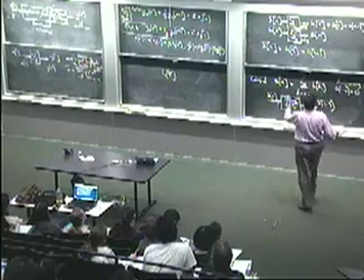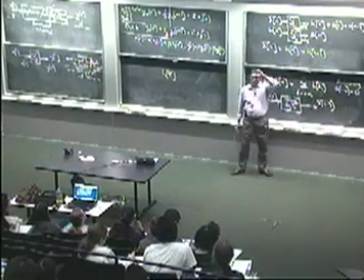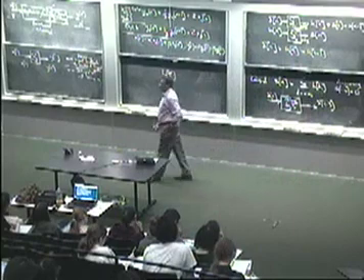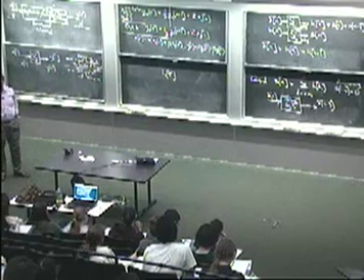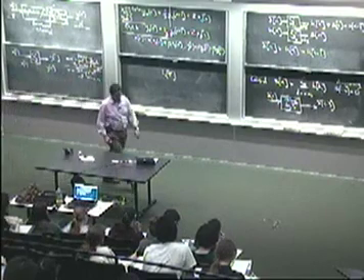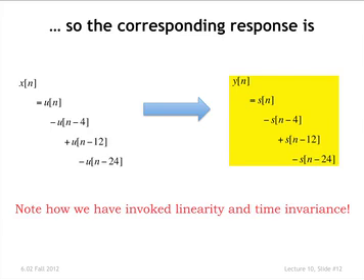So then it's back to this game again, right? If the input is a linear combination of unit steps, scaled and delayed, then the response is going to be the same combination of unit steps. So that's what the response will look like. So here's the unit step u[n] gives rise to s[n]. Therefore, minus u[n-4] will give rise to minus s[n-4], and so on. So knowing the step response, you can actually say what the response of the channel is going to be.